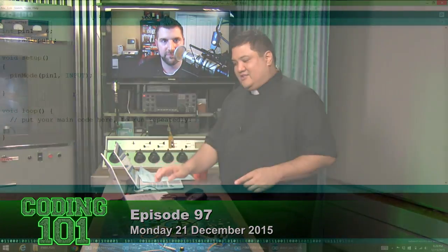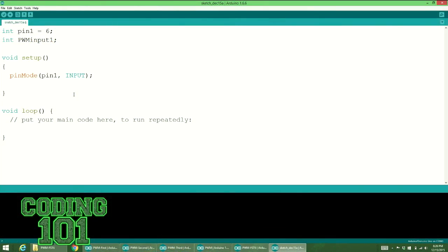All right, so let's go back into the setup. The other thing we want to do is we need a way to get output. And what we're going to do is use our friend Serial. So Serial, yep, and we love Serial. Serial.begin, and again, it changes color because it knows it's a reserved word. Begin is going to open it up, and I'm going to set it for 9600 again. So now it's going to open up a serial port, set for 9600. In this particular case, I think I'm connected on COM3. That's what the USB port gave me.